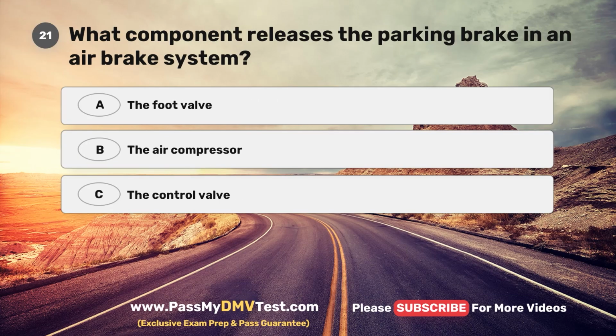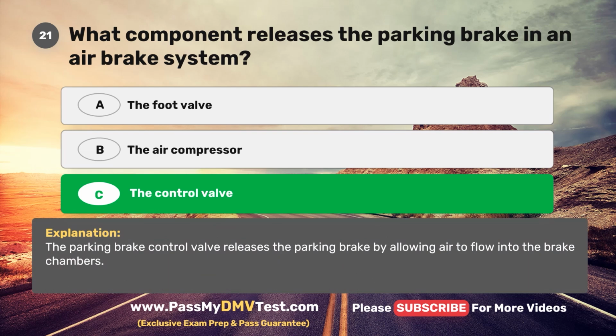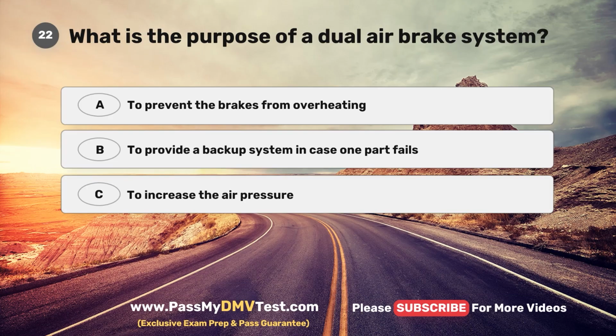Question 21. What component releases the parking brake in an air brake system? A. The foot valve. B. The air compressor. C. The control valve. The correct answer is C. The control valve. The parking brake control valve releases the parking brake by allowing air to flow into the brake chambers.